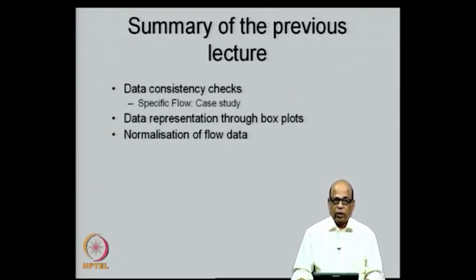this concept to examine the consistency of data. This particular method is especially useful when we are talking about large catchments where a number of gauges are recording the flows, and then we would like to examine whether the flows are in fact consistent with each other as recorded from various gauges. And we took up the case study of the Narmada basin and examined at various sub basins how the specific flows compare with each other.